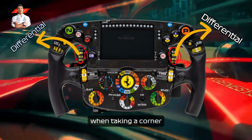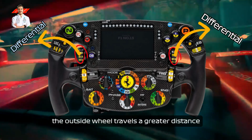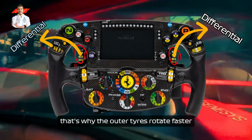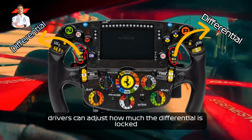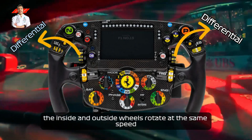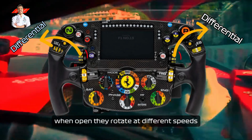Differential. When taking a corner, the outside wheel travels a greater distance than the inside wheel. That's why the outer tires rotate faster. With this setting, drivers can adjust how much the differential is locked or open. When locked, both the inside and outside wheels rotate at the same speed. When open, they rotate at different speeds.